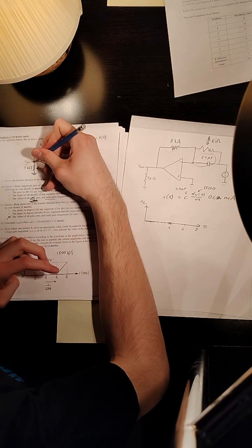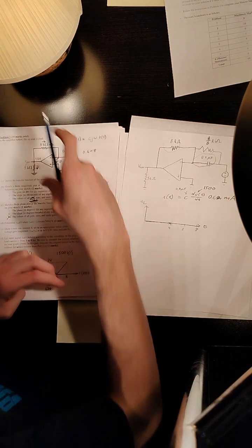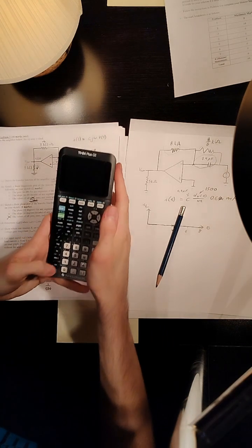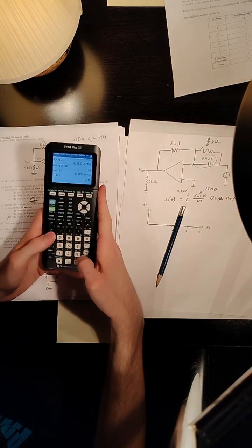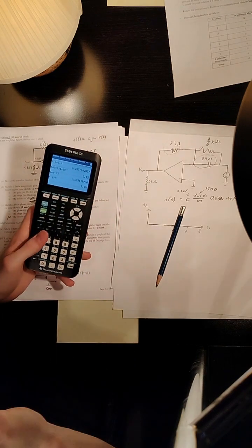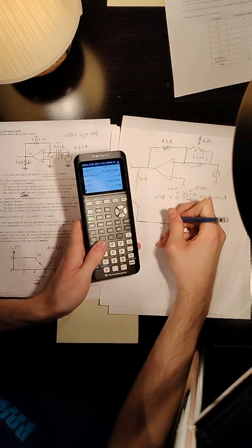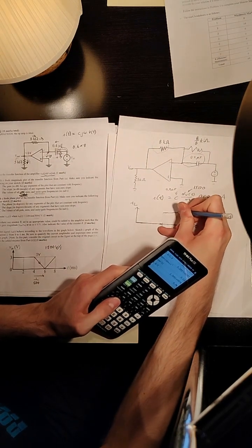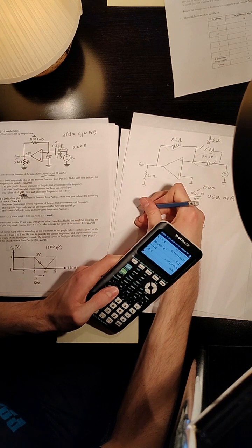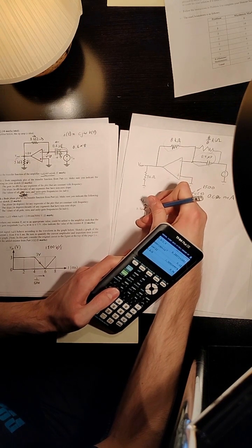And then you're sending that across a 5 kilo ohm resistor. So if you wanted the current, you would divide 4.8 divided by 5, and that would give you 0.96 milliamperes. So this would take a jump up and plateau off like this, and that would be 0.96 milliamperes.